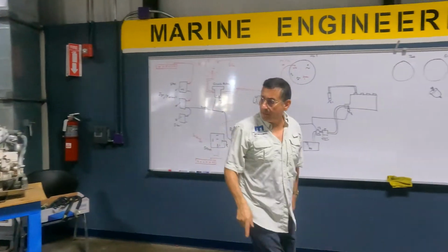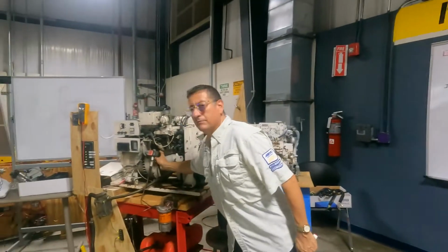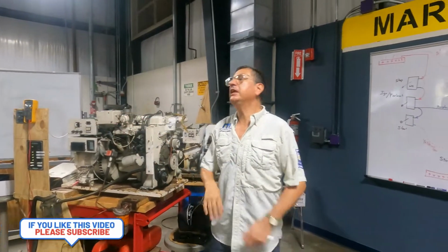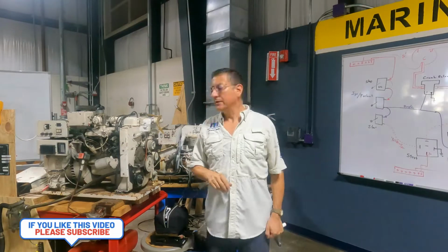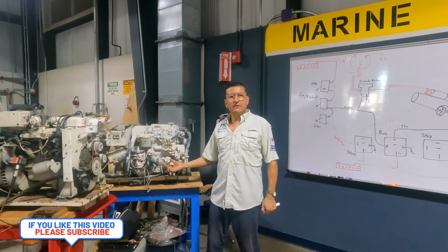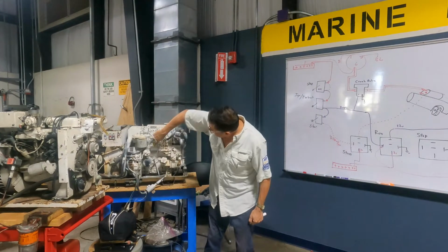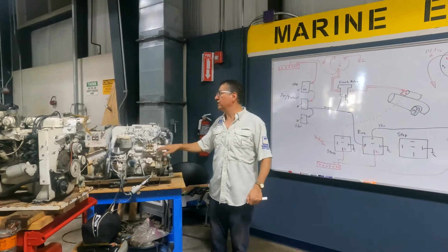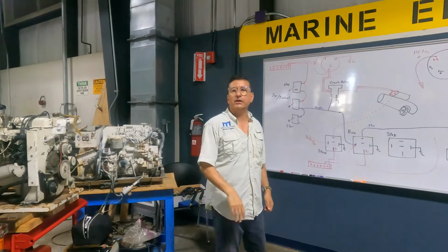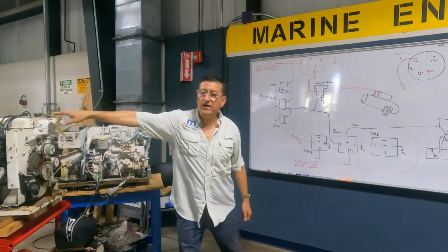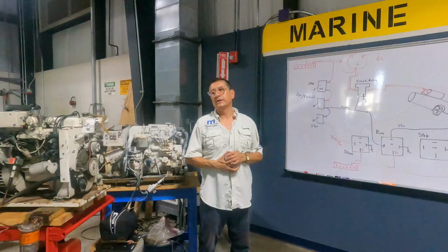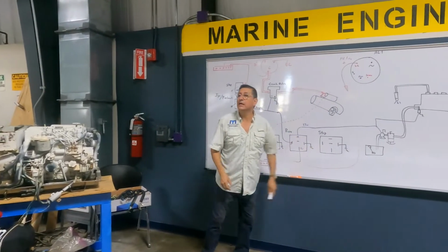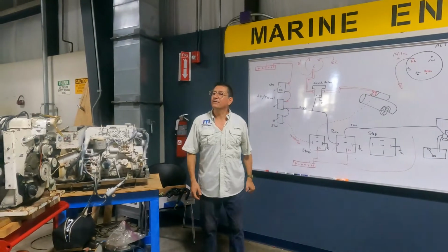I need to stop the pump and cut this solenoid. And finito, the engine stops. I need to stop the transfer pump and stop that solenoid, so the fuel does not enter the fuel injection pump and the engine does not continue running. If it's diesel or gasoline, it's exactly the same. Pay attention. How do I interrupt? With the stop relay. Remember, guys, follow me.